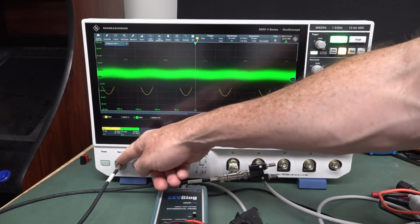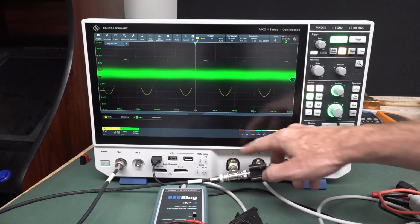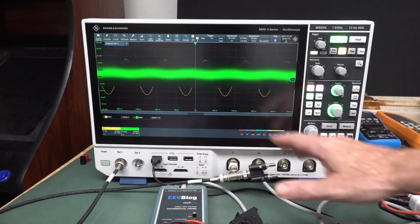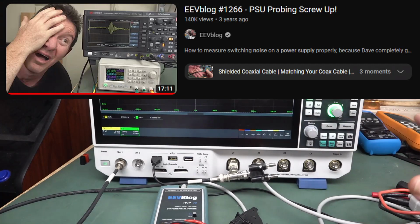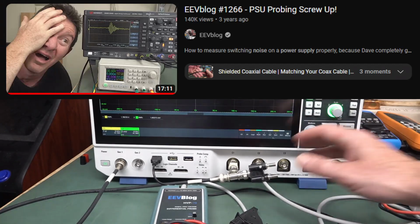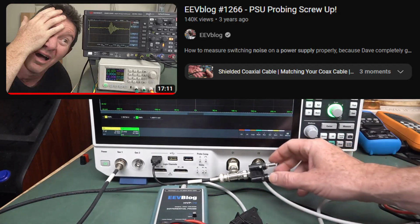And then we want to feed the output of the SigGen into a 50 ohm terminated load so that we don't have any transmission line issues whatsoever, no reflections causing problems. I've done videos on that and how you can goof that up in noise measurements and stuff like that. So I'll link that video up here and down below if you haven't seen it.